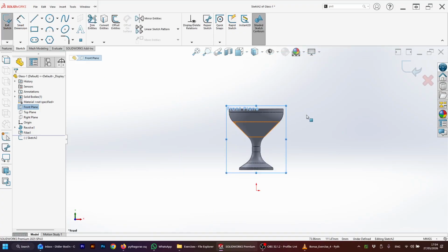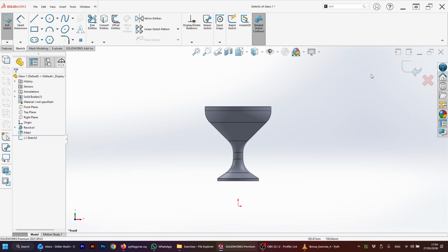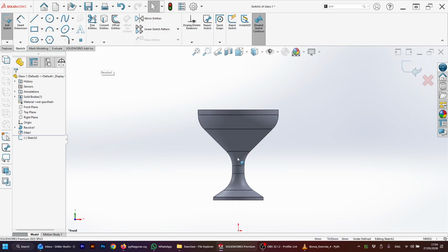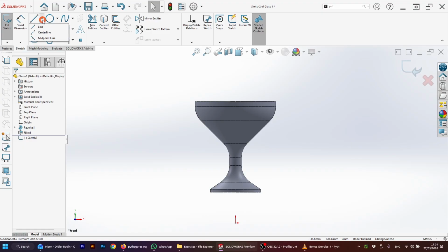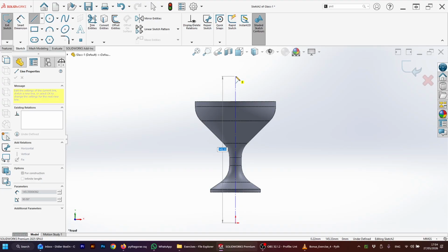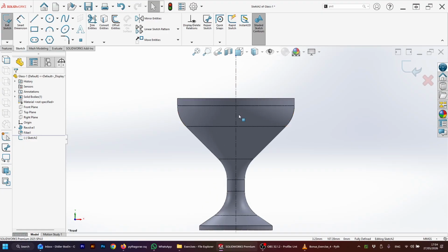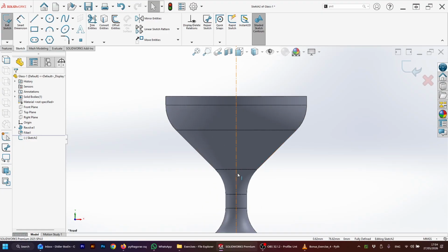Click on sketch. Here it opens a sketch for me. I can see the red dot, the icons on the side, sketch 2 on the top. I'm doing this on purpose because at the beginning when we start building in 3D, it could be confusing to know whether I am in a function or in a sketch. So these are the visual cues: red dots, icons, sketch 2 and the name of the file on the top. So now that I have this, I want to sketch the shape.